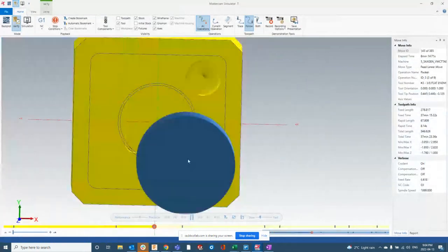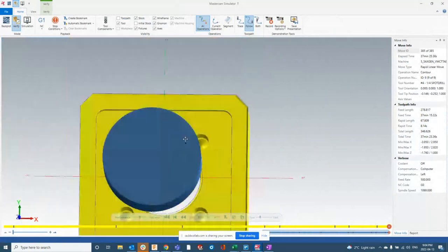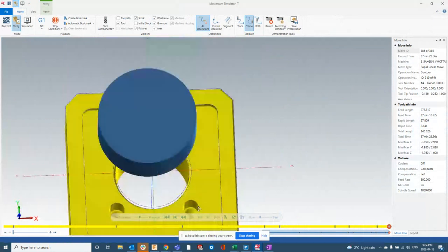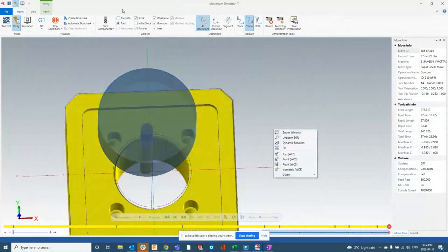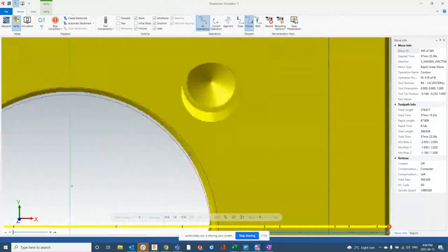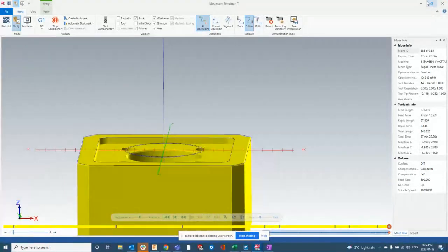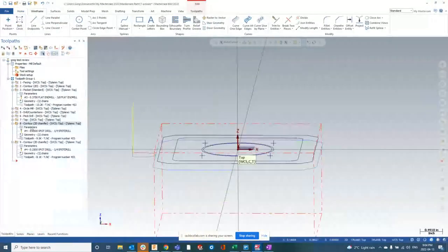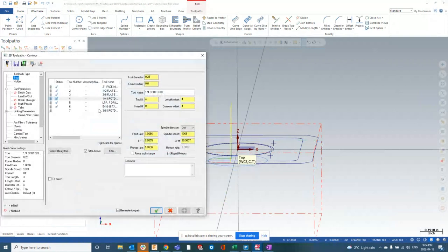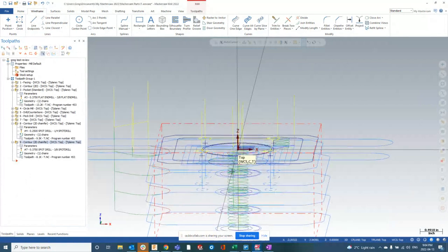So actually, this chamfer, it's a little bit smaller, but it's almost there. Let's change it to 3. I'm actually curious now. Let's go back. So this one, let's go to a 3/8 spot drill. Hit OK, and let's watch it.